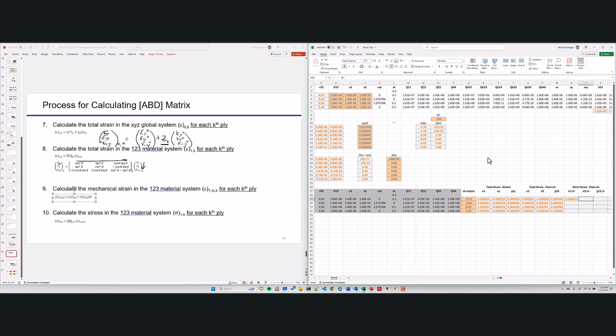And then E2 is equal to the total strain in the 2 direction minus alpha 2 times delta T. And then my gamma 12 is equal to the total strain minus alpha delta T, but there is no alpha 1, 2 because it's an orthotropic material, right? There's no extension-shear coupling in the 1, 2, 3 system. So don't get confused. Another place where a lot of students get confused. Alpha 1, 2 is 0. That's why we just don't put it in. So the minus 0 times delta T is still a 0. So it is just the total strain in that direction.